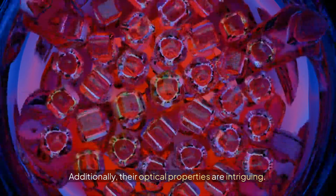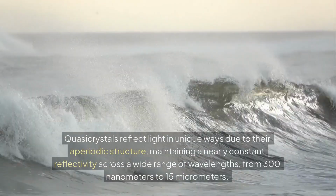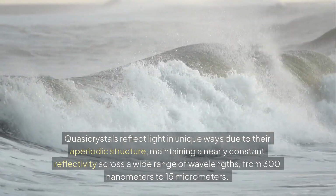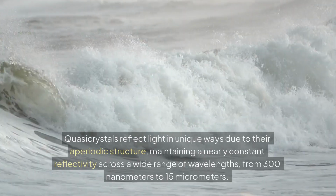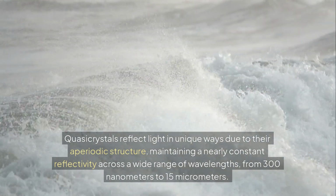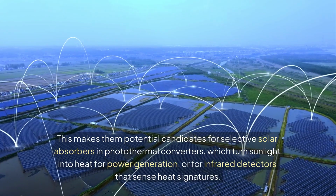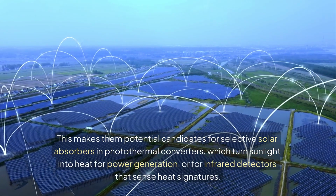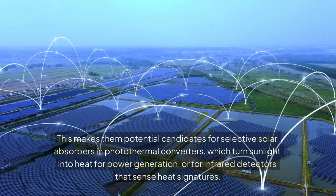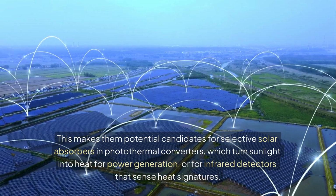Additionally, their optical properties are intriguing. Quasicrystals reflect light in unique ways due to their aperiodic structure, maintaining a nearly constant reflectivity across a wide range of wavelengths, from 300 nanometers to 15 micrometers. This makes them potential candidates for selective solar absorbers in photothermal converters, which turn sunlight into heat for power generation, or for infrared detectors that sense heat signatures.